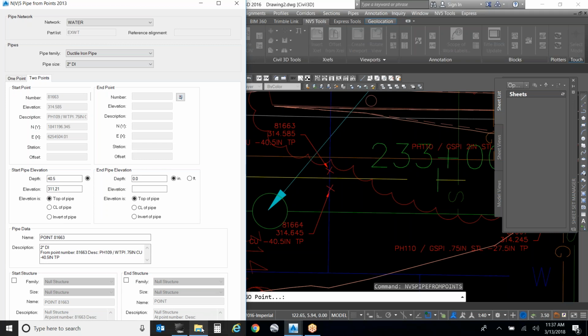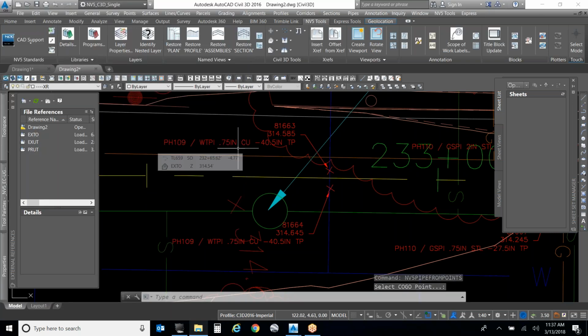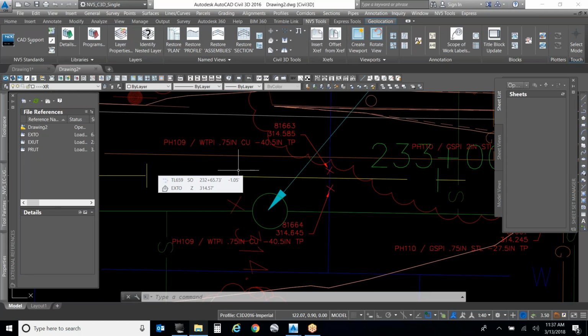We've had that come through on a couple of SoCalGas jobs because the crews thought you were still doing P-sub requirements versus SoCalGas and SDT. And that's also an interesting point: make sure you separate the 2 workflows of design versus as-built, because the data that you receive is going to look completely different. So this was a design application, a standard pothole. It came back already filled in, and we have the information literally painted on the asphalt. So that's the information we're getting. We don't typically shoot the actual item. We're usually shooting a marking on the surface. Correct. And that description, they're picking up from the paint that's been painted on the asphalt.